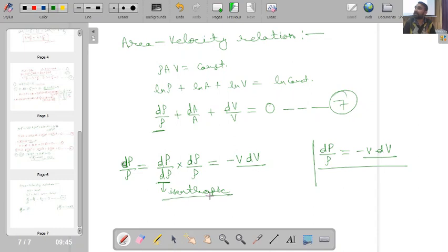Is this point clear why I am saying this? Because I have not included the conduction term in my energy equation, there is no diffusion of heat, so no gradients of temperature are present. And I have considered an inviscid situation, which tells that we will not have friction and other dissipative effects for diffusion of momentum. We are not doing any external heat addition or removal. So my situation is reversible adiabatic, which is an isentropic situation.